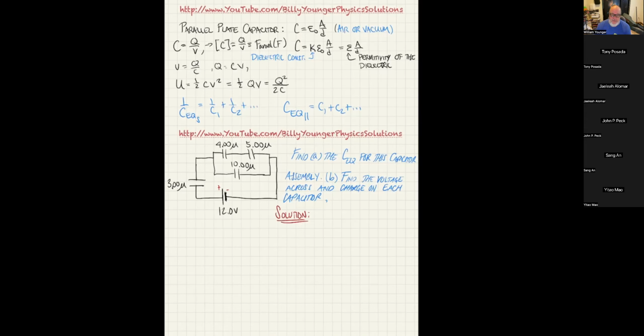So this left side of this battery, the positive side, acts just like a big heap of positive charges. So all the positive charges want to run around away from that and then establish all the voltages as best they can across capacitors. And then those are going to scare the positive charges on the right hand sides of the capacitors, or the top in the case of the 3 microfarad capacitor. They're going to scare the positive charges away from it and force those charges to run to the next capacitor, and so on and so forth.